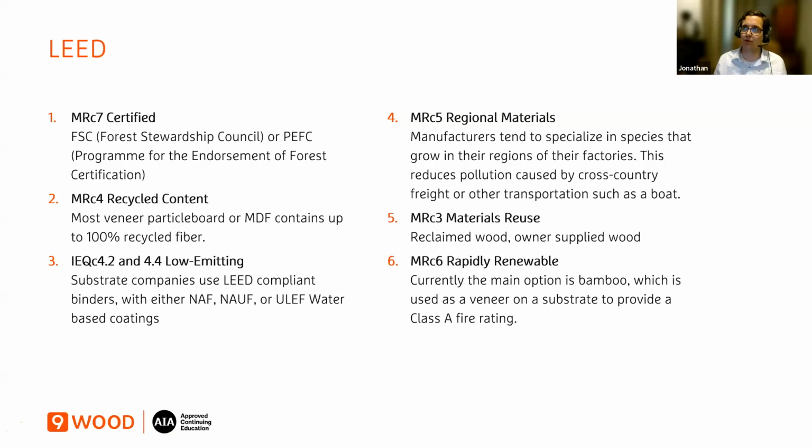LEED, right off the bat, I'm not going to cover sustainability, just going to hit LEED here. Sustainability is a pretty big topic and important with wood. But with LEED, there's two credits that are probably the most common and easier to get with wood across probably all the manufacturers. The first one is the certified and then the recycled content. So the veneers come on either particle board core or MDF, and that generally can achieve the recycled content point. And then the certified either comes in FSC or PEFC.